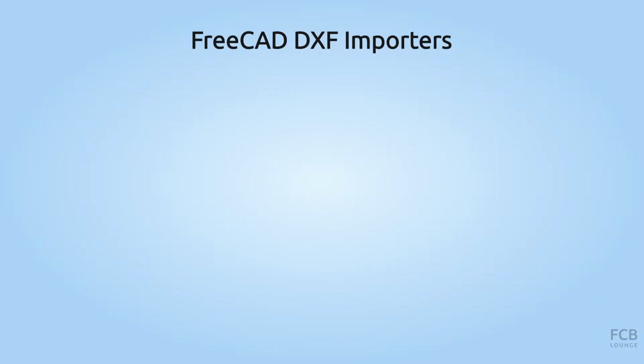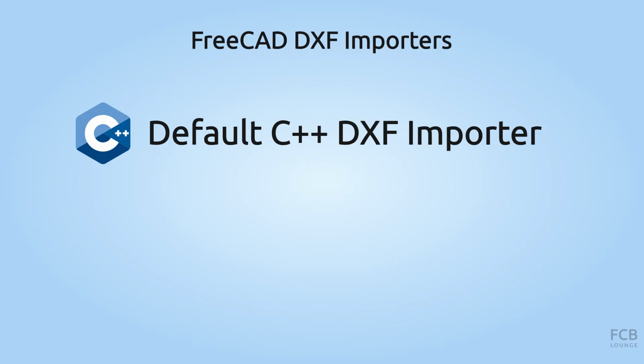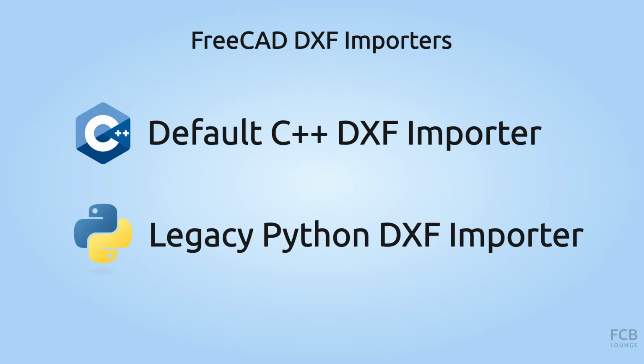Before we start, it's important to note that there are two DXF importers in FreeCAD. The default C++ DXF importer and the legacy Python DXF importer. The default one is faster, it's more robust, but it does not have all the features of the legacy Python DXF importer. So in the first part of the video, I will show you how to use the default DXF importer, and then in the second one, I will show you how to use the legacy DXF importer.